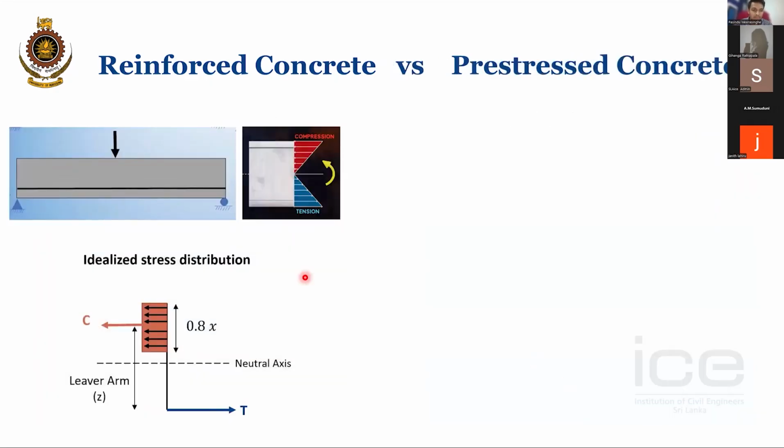If we illustrate that further, in a reinforced concrete member bending downwards, the neutral axis passes through the centroid, if it is a rectangular section. Above the neutral axis the material is trying to squeeze in, therefore it is compression, and below it is trying to stretch, so the material is under tension. You will have a triangular stress distribution, with one part in compression and the other in tension. This is the strain distribution, and at failure we idealize this to be a rectangular stress block.